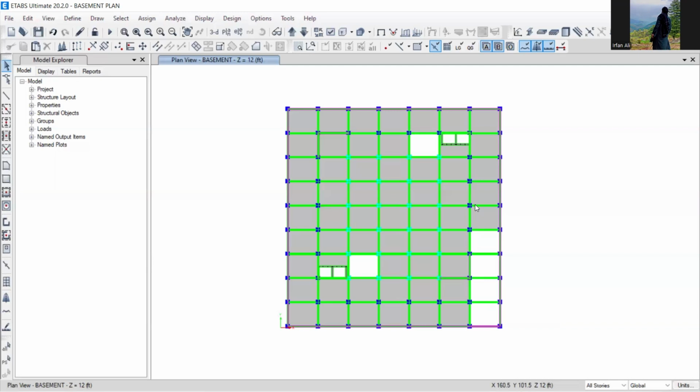Then you have to apply the strategy that we have applied. When the architect has an issue with larger columns, you say in clear words that if you do not want to increase the column sizes, then the reinforcement in the lower stories or in the smaller columns will be higher. Too much reinforcement will have to be provided, so you have to select either larger columns or a huge amount of reinforcement. Obviously they will go towards the larger columns because they do not want the client to have an uneconomical structure.